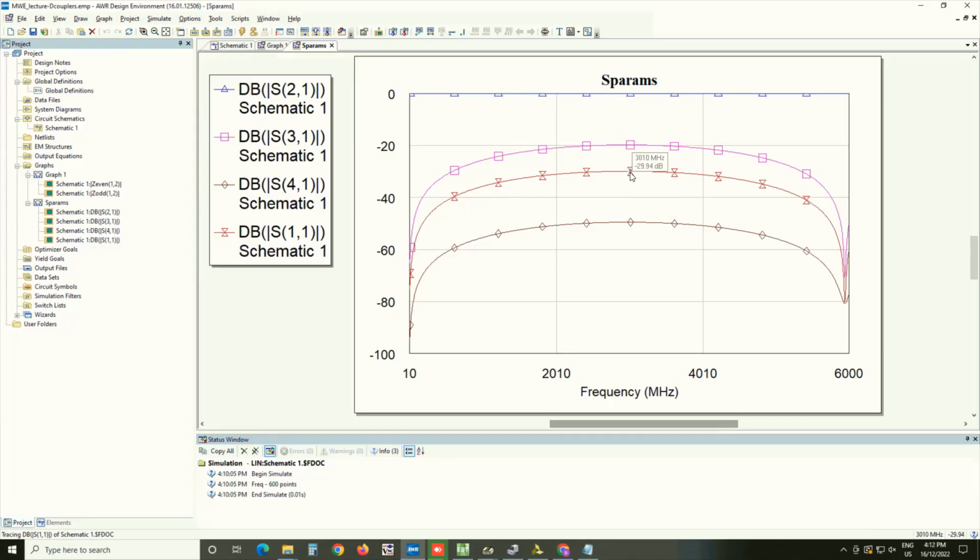It's pretty decent. Okay. And then these numbers sort of start to deviate as you go away from the intended operation, but it still works as a coupler because the matching and the isolation are still okay. It's just that the coupling value is now going to be smaller as you go away.